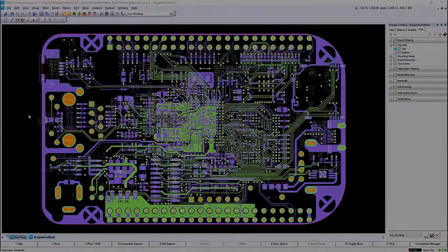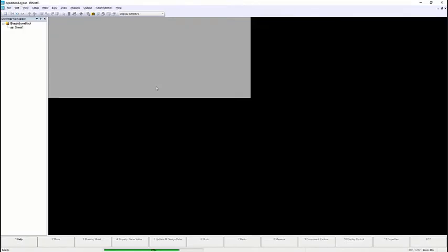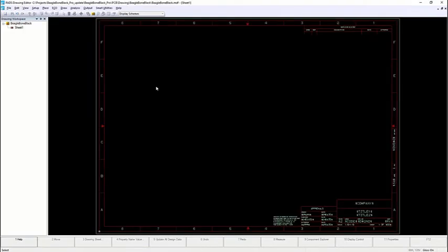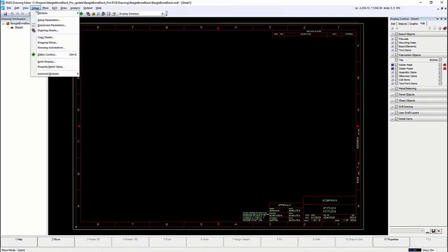A serious issue that tends to arise between board designers and manufacturers is miscommunication. Sometimes, assembly engineers will not communicate all design changes back to the design engineering team, causing issues with the saved PCB design database. In order to produce information in a way that is clear to review and understand by both parties, PADSPro allows designers to create unique drawing sheets and define panel data with Drawing Editor and FabLink respectively.